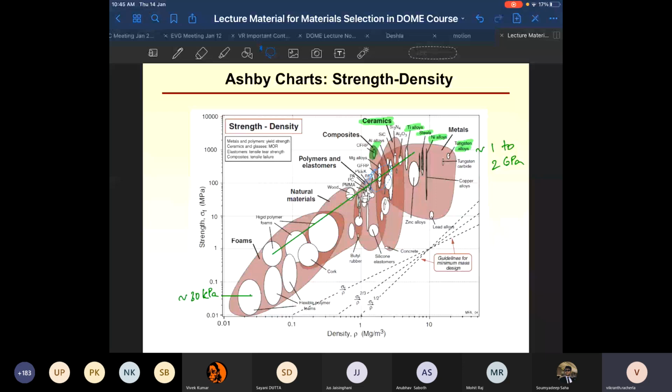Now between steel alloys and aluminum alloys, if I put this in the middle of the steel thing, you can see that depending on the choice, if you pick an appropriate aluminum alloy, then you can actually get a lower weight for an aluminum structure as compared to a steel structure.